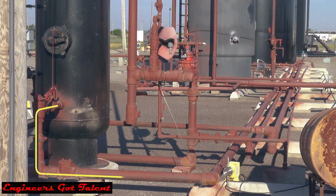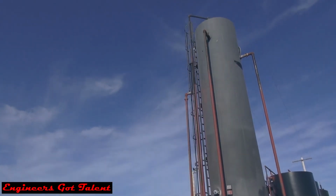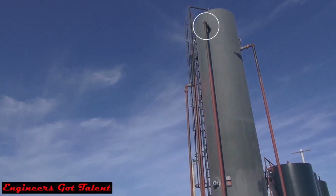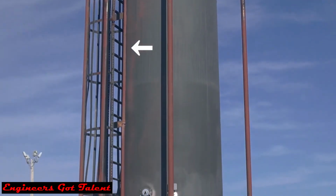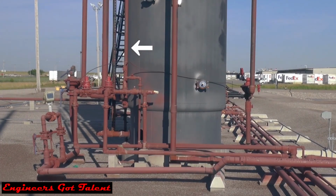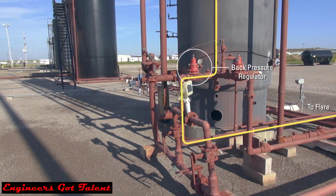The emulsion flows into the treater. At the very top of the treater is a baffle. At that baffle, the gas, which again is lighter than the liquid, breaks out of the top, comes down this pipe, comes down to here. One valve takes us to sales, the gas to sales. The other valve takes us to flare.